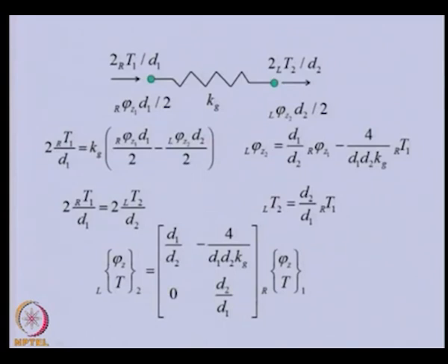So this is the linear spring having this stiffness. Now at the two ends we have these linear displacements, because if we multiply the angular displacement by the radius we get the linear displacements of the two ends of the spring, and if we divide the torque by the respective diameter of the two gears we get the force.